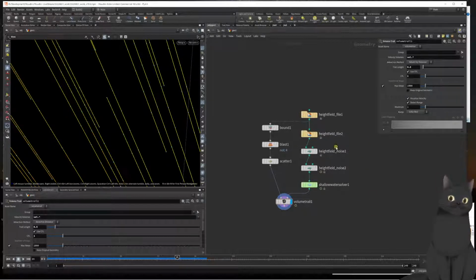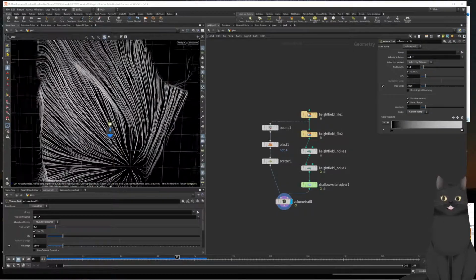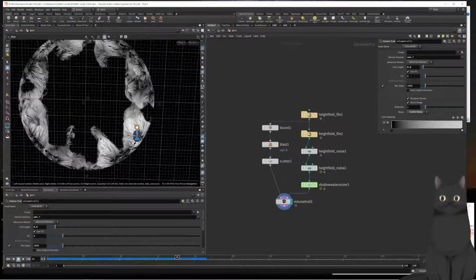Also, down here, what I did is instead of using the infrared standard ramp here, dialed in a custom color ramp, which I can do by going to custom ramp here. And then I have a few points here with color down here. Made sure the interpolation here was set to B-spline to make the interpolation of the colors a bit smoother. And then I added 3 more points. And then I started out with, I think, a greenish color, something like this.